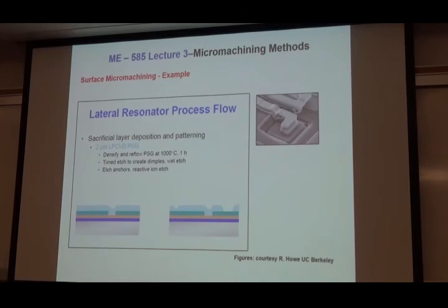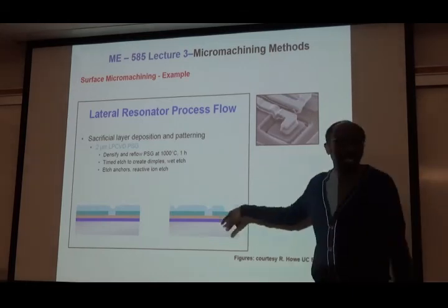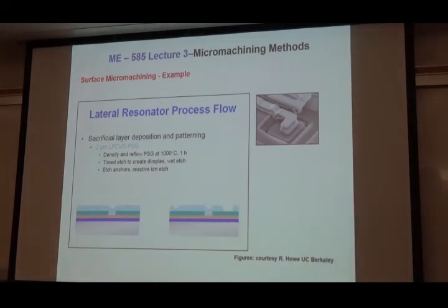People worry about that. Okay, how do you prevent that? Just put a guard, kind of a seal. And then what you're going to seal is just bombard it with additional high concentration N plus. So that worked. But then again, the insulation was not adequate, 0.5 micron. So we say, okay, let's do a low stress nitride.